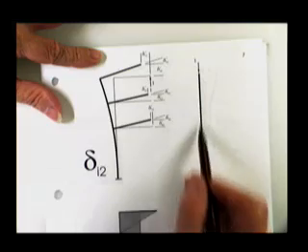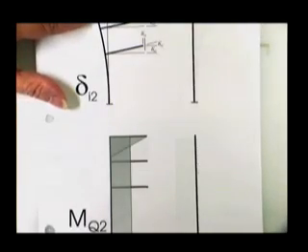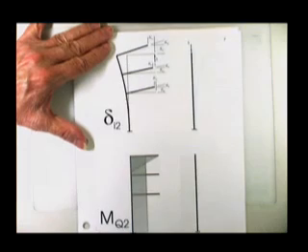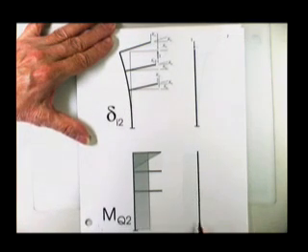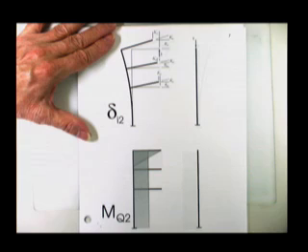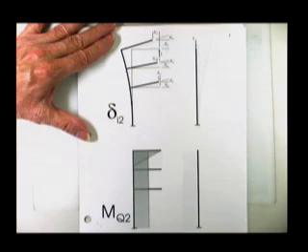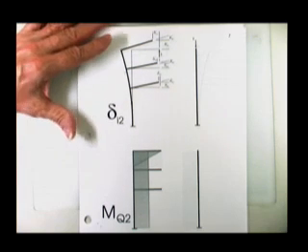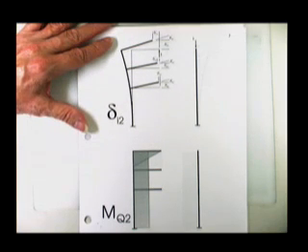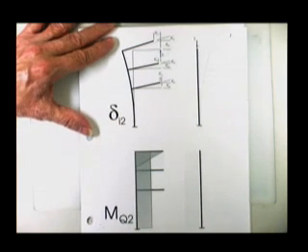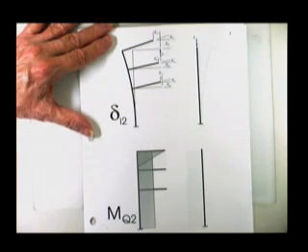Therefore, when you push down on this member, lo and behold, you get nothing but axial force. You get no bending moment. This member does get very, very slightly shorter, PL over AE, but axial distortions in these members are usually very small and are usually ignored. You don't have to. You could add the PL over AE terms to the terms you have now. But bending so far overpowers it usually that usually just the bending stuff is considered.